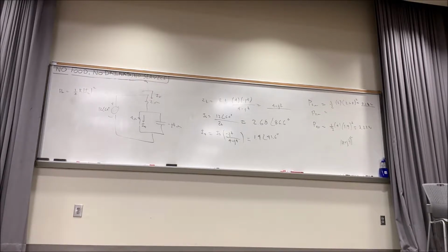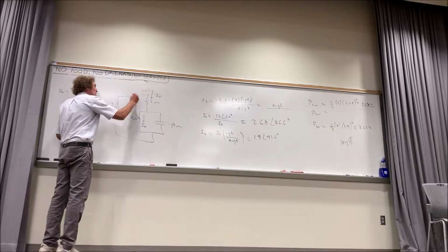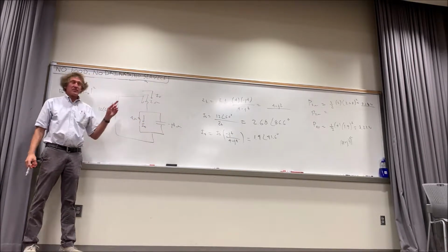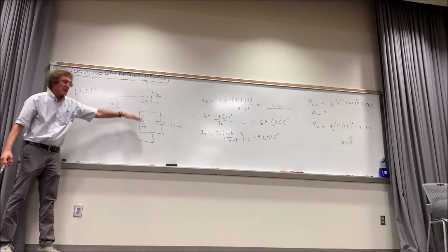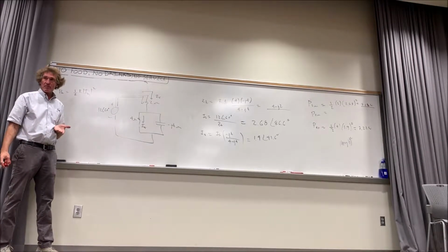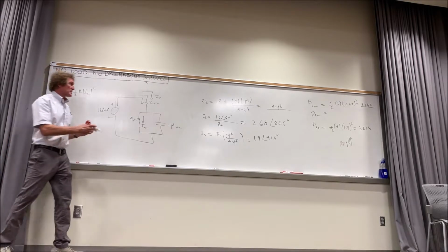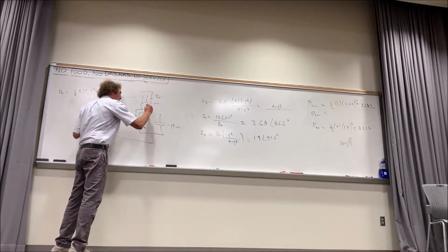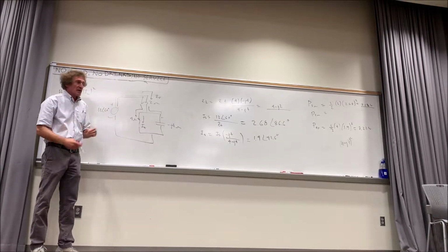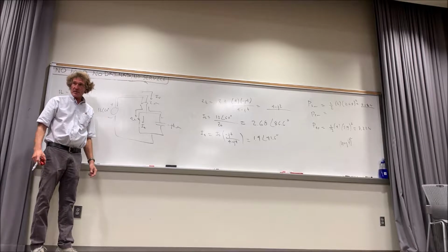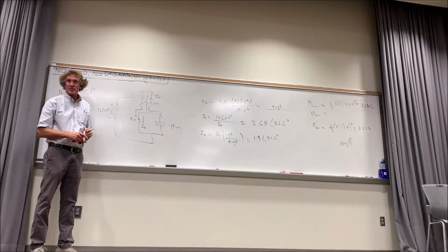So why was that the IS value of the total circuit? This is the current flowing through the 2 ohm, right? That current divides into these two things, but if I want that current, I find the total impedance divided into 12. When it comes around on the other side, it passes through all of those. Current into is equal to current out of, so the same current is flowing in every portion of that circuit.